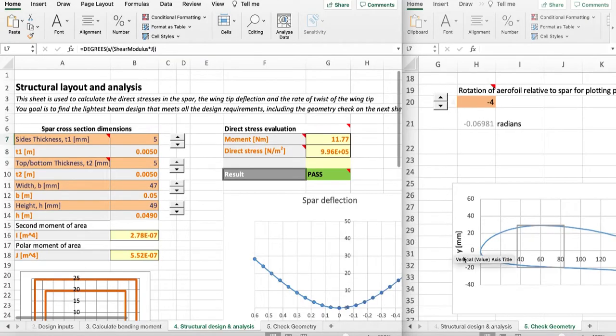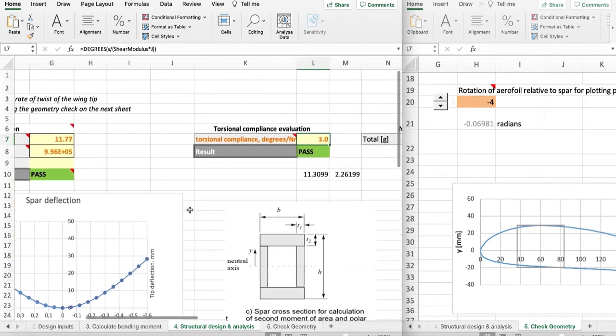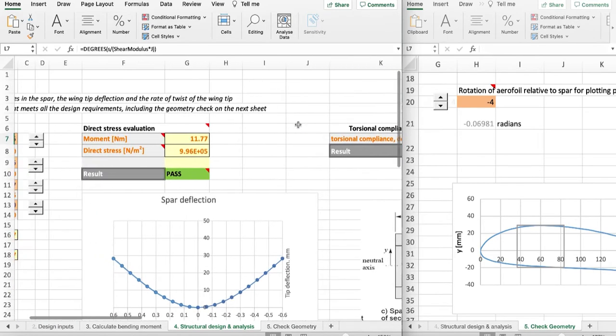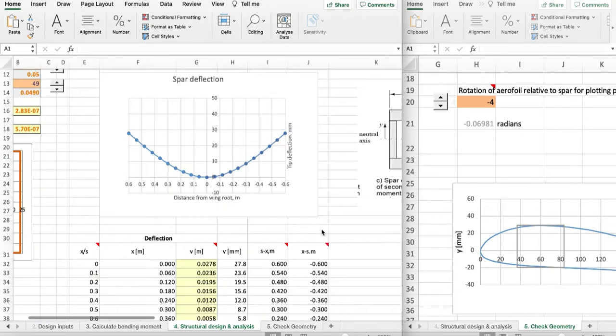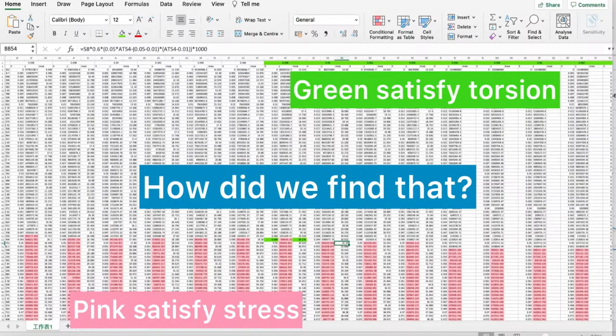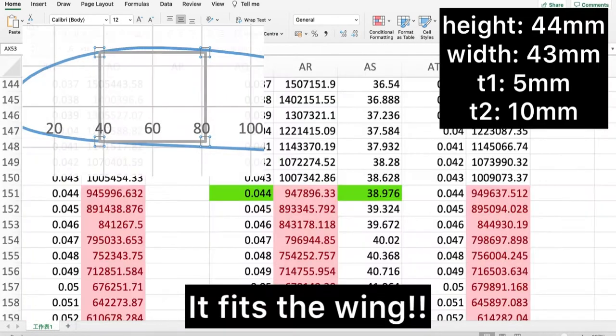The second stage is the preliminary design stage. Having made initial decisions about the configuration of the wing, it is important to decide on the geometry. This stage allows us to make predictions about the performance of the wing and optimize its dimensions to satisfy all requirements. In order to better understand how the geometry affects the behaviour of the wing, we went through beam theory, and later used Microsoft Excel to obtain numerical data. Using Excel also allowed us to list out every possible configuration for the spar, which made it easier to decide on the final dimensions.